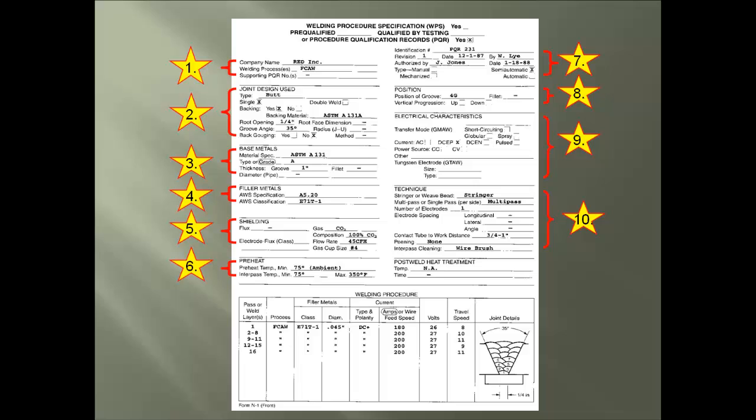If flux core or gas metal arc welding processes are used, what is the contact tube distance from the weld joint? Is there any manual tooling to the individual weld bead, called peening, being used? And closing with the means of cleaning the individual passes.